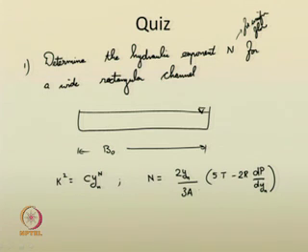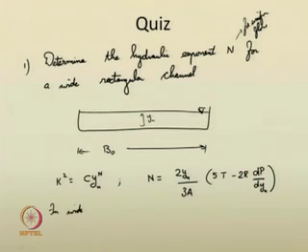So, in this, what are the criteria for the wide rectangular channel? You just substitute that. For a wide rectangular channel, your hydraulic radius is almost equal to your normal depth. Also, the change in wetted perimeter with respect to depth in a wide rectangular channel, what will it be? For a wide rectangular channel, dP/dy is approximately equal to 0.